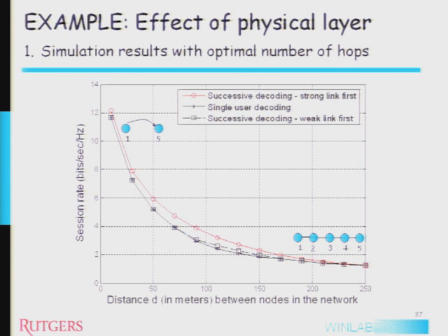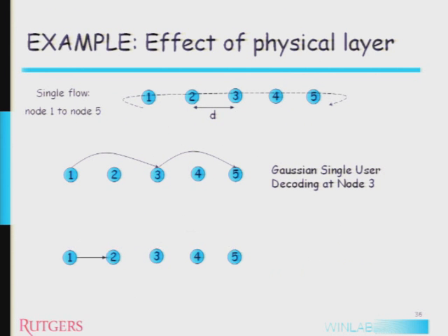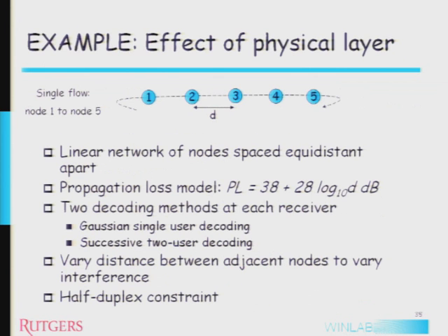Well, let me get that. So the signal-to-noise ratio is 20 dB for one hop, right? At what distance? I think it's around 50 meters. And what exponent did you assume? 2.8. So when we go from 50 to 200, which is a factor of 4 in distance, I take 6 times 2.8. That's 3. Let's call it 3. Okay, so it's 80 dB. So 200 meters is close to 0 dB signal-to-noise ratio for a single hop, right? Okay.